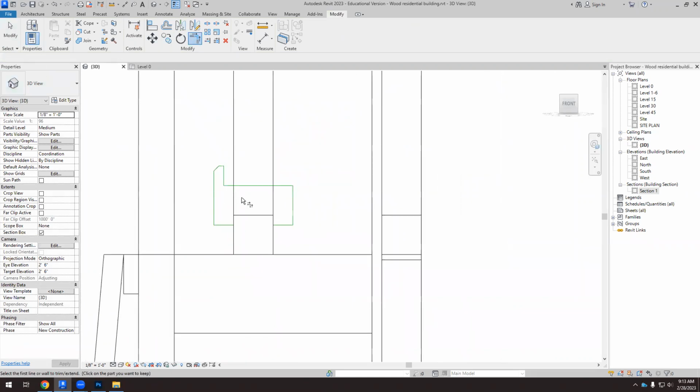Okay, so you see that I have created this. I have used this element to fix the fixed part of the window frame. Okay, and then I created this line that is fixed on this wooden element that I created before. So on the window, we are going to do the same. We're going to use a sweep, and we're going to sweep this profile along the perimeter of the window. So that's number 3, and then I'll do number 4.